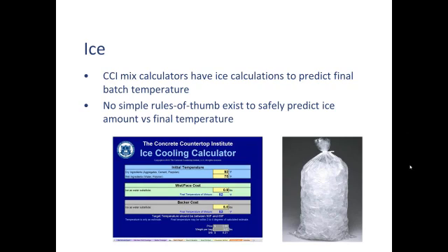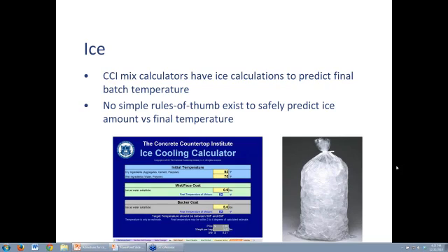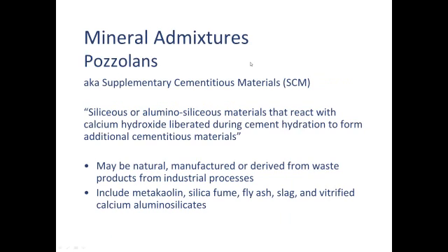Now, in terms of just taking a CSA-based concrete and casting it in your shop, you could cast it at, say, 32 degrees. I wouldn't necessarily cast it outside, where you've got to still deal with proper cold weather concreting practices. I'm not talking about casting in extreme temperature conditions. I'm talking about just making it so we have lots of work time. All right, so those are the admixtures that really focus on the work time up front.